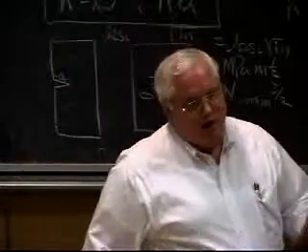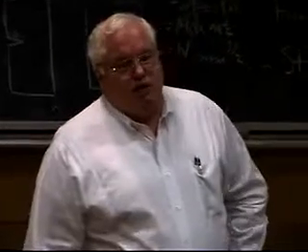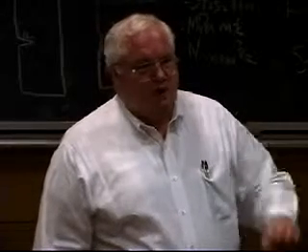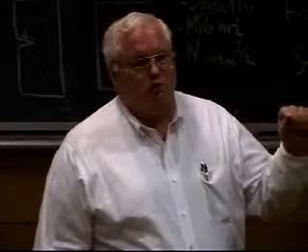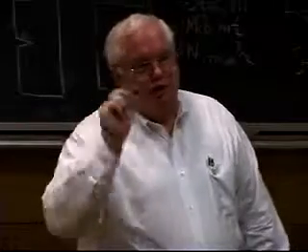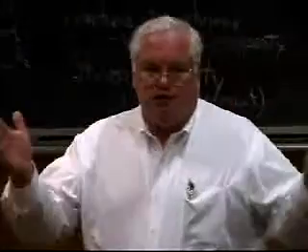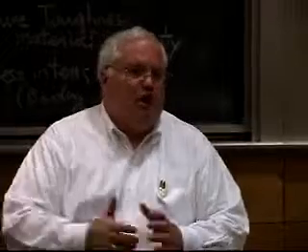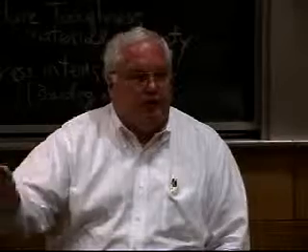The answer in between, if you've got lots of porosity in something, is such a wide variation that it's very, very difficult for someone to calculate it in those cases. Typically, in a welding spec, it'll say something like no more than 6 pores per 12 inches of weld. Well, you're talking pores that are less than 1/8 of an inch in diameter, because if it's greater than 1/8 of an inch, it's rejectable, usually. So 6 in 12 inches means on average they're every 2 inches apart, so they actually are individual. Now, if they're clustered, and sometimes the spec will say, if they're clustered, it'll have some other rejection criteria.